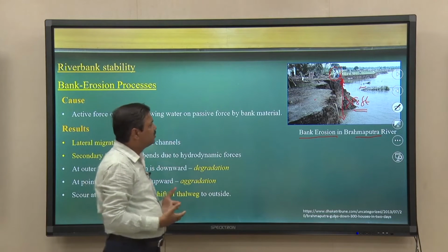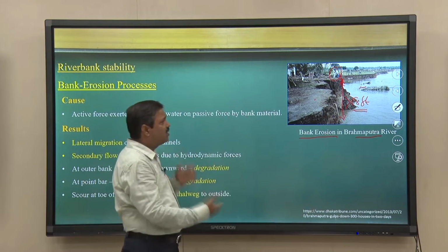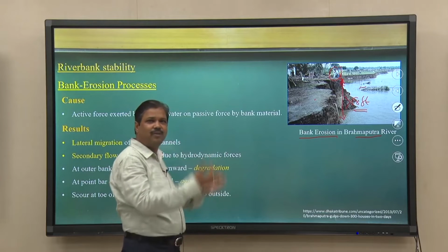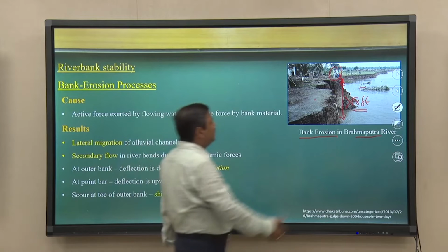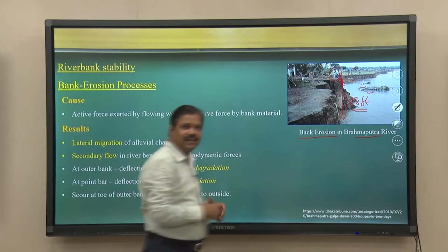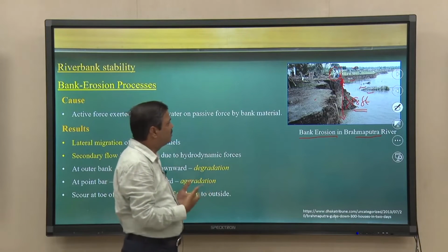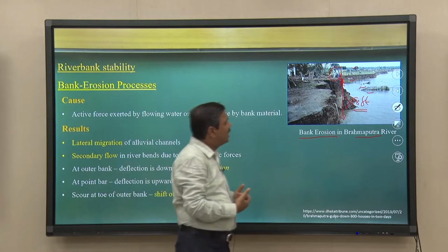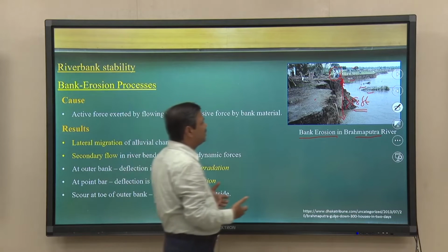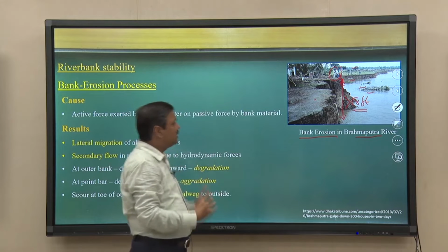Just look at it. It will be more than 18 feet, and that is the undercutting of the rivers that is happening, and this causes mass cantilever failures, cracking, even trees falling down. These are similar photographs you can see in many parts of the Brahmaputra basin and the Barak basin, having such high erosion rates during the flood periods or the receding of the flood periods. Let us understand the process.